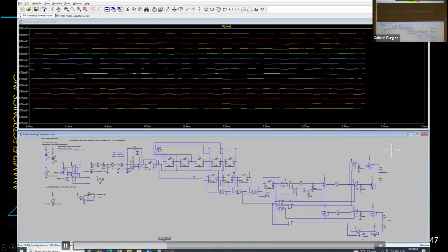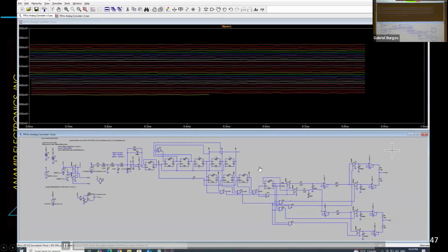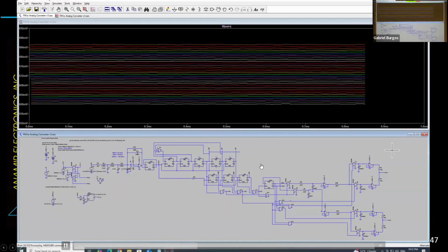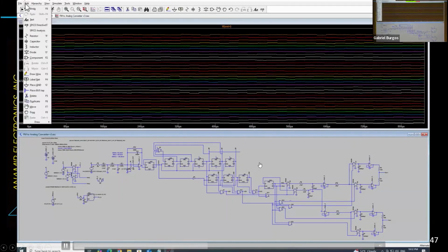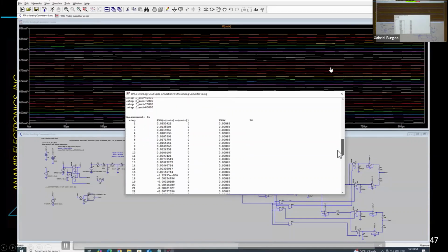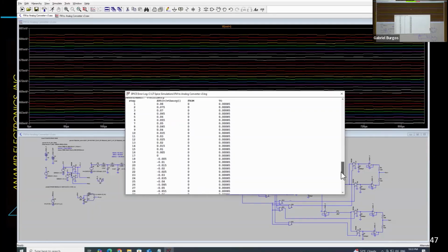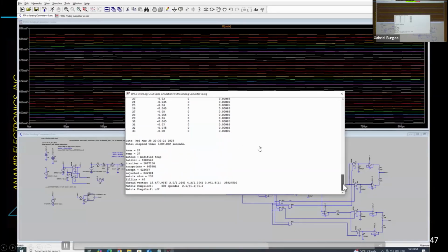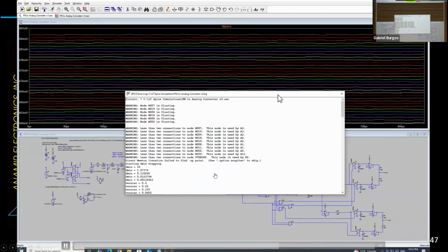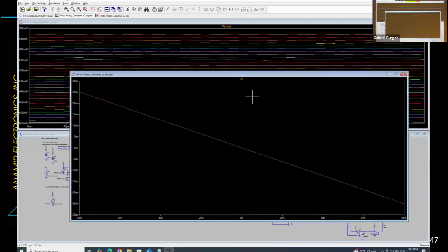We vary the frequency of input, and we get these, which are kind of pretty. I incremented the frequency a little bit every simulation run. LTSpice is able to log all that information, measuring the RMS signal level of each case for each frequency and making a report about that. Then I can graph that. Here I graph that. You can see it's a very straight line.